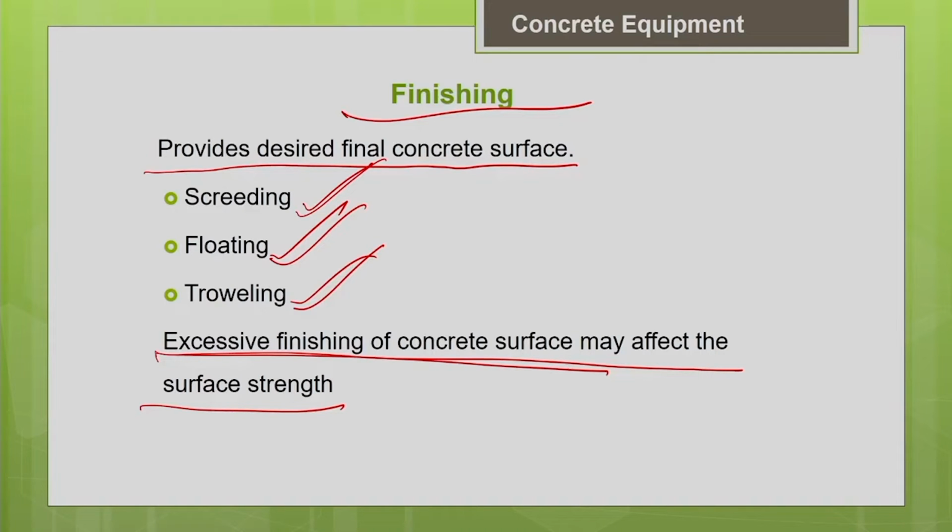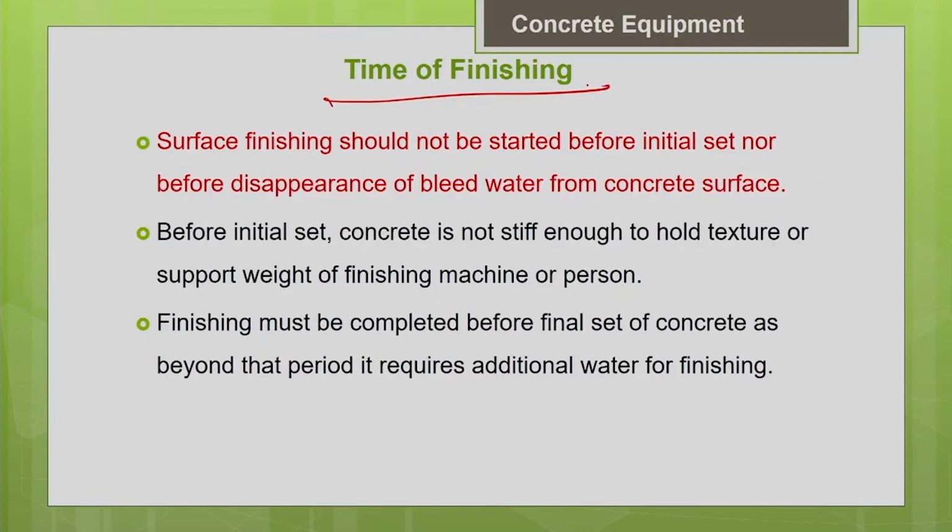Let us discuss the different steps of finishing one by one. The first thing we are going to discuss is the time of finishing. When should we start the finishing operation? The surface finishing should not be started before the initial set. Before the concrete attains its initial set, we should not start the finishing.